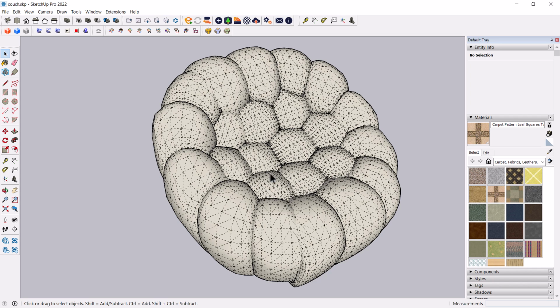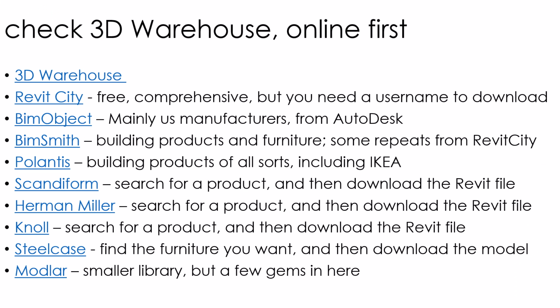In fact, I know you will run into problems if you try to use a material, for example, like the one they've applied here, that is meant to be fabric-like. What will happen is it will reorient the material over every single facet, and that's a difficult problem to solve. So despite the problems of SketchUp objects, I would strongly recommend checking them, and you can absolutely render them as solid materials in Revit without any problem of that faceting. All the weird lines disappear, and that works quite well.